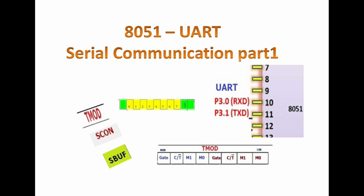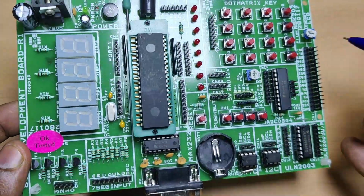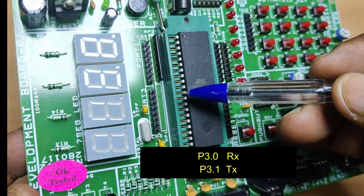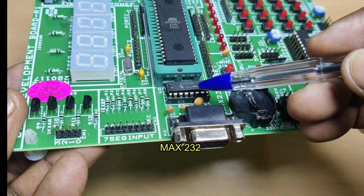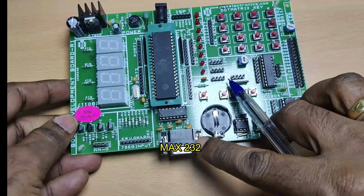Hello all, this video is on 8051 UART serial communication. This 89S52 has got UART pins at port 3, that is port 3.0 is the RX pin and port 3.1 is the TX pin. And on board there is an RS232, that is a MAX232 IC, to convert it into RS232 levels.